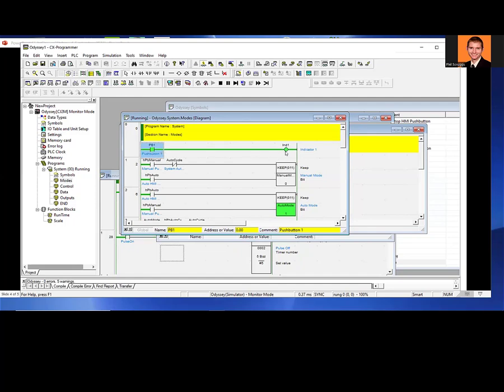That's another very unusual thing about Omron that is very different than Siemens, Allen Bradley, Beckhoff, whatever. I can be in simulation and I can set a physical input. Since I'm simulating, it knows: don't go out and read the physical input table for the push buttons and the indicators. Don't write to a real indicator. Go ahead and just write to this address.